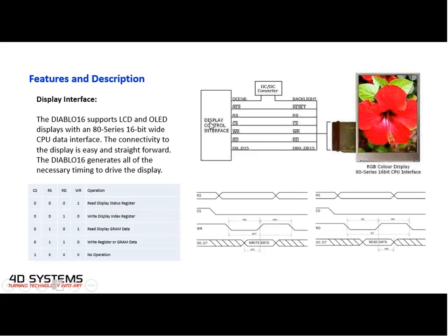So this is our Diablo, and it also has control for the DC to DC converter for the backlight control. Here you see at the left side the logic table, what must be the state of chip select, reset, read and write operations. So it's straightforward. The Diablo16 generates all these necessary timings to drive the display.